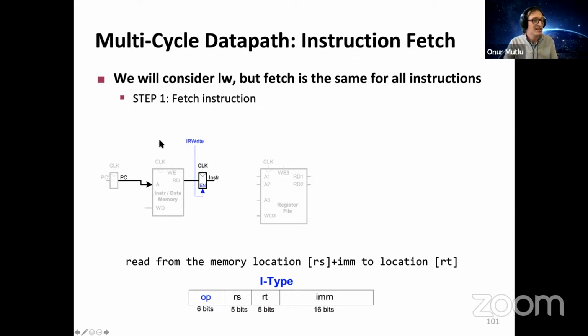So a fetch instruction in this case takes 1 cycle, as you can see. It could have taken multiple cycles also. We could actually say this takes multiple cycles, and we will see that later on toward the end. But in this case, it takes 1 cycle, as you can see. Okay, that's beautiful, right? We're not constrained anymore. So the cost, of course, is the register that we've added so that we can latch the intermediate result.